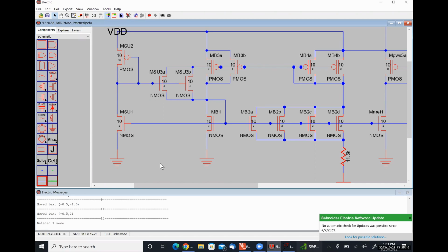So how I personally did it is I just divided it into little blocks. So I'd make that strip, make all those connections, and then after I had made how they were connected to each other, I connected it over here. And then I made this strip of transistors. After I got all their connections correct to each other, then I connected it, and so forth and so forth and so forth. It's really easy to make one small connection and then half your circuit has drain currents of 0 because one pin is in the wrong place. I say that because that happened to me yesterday.